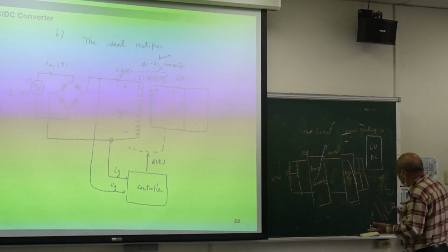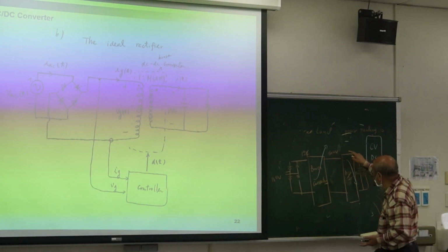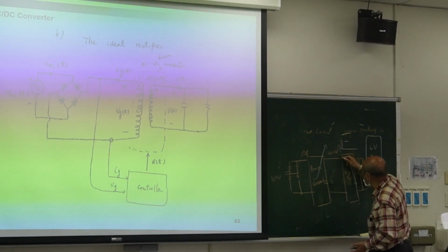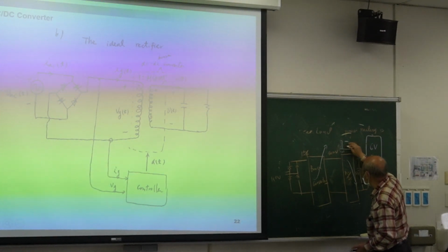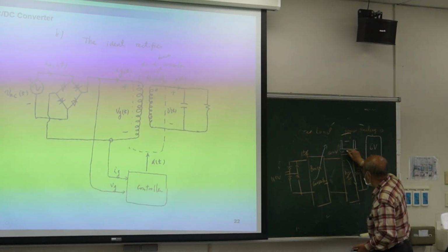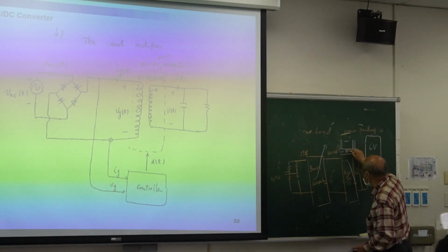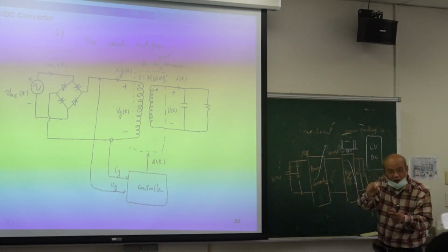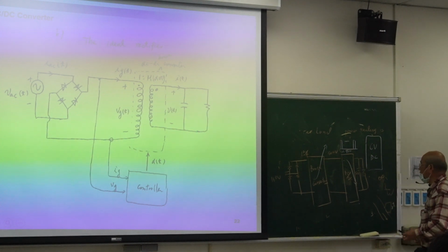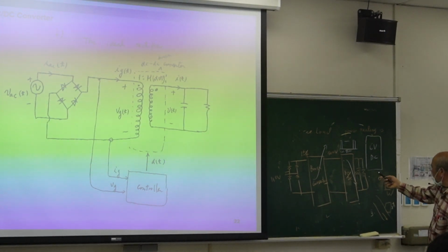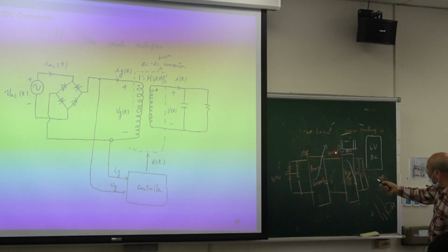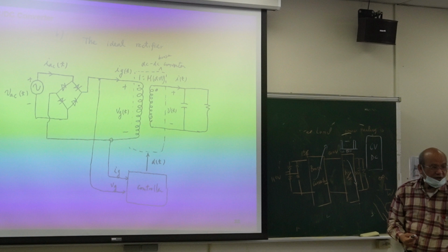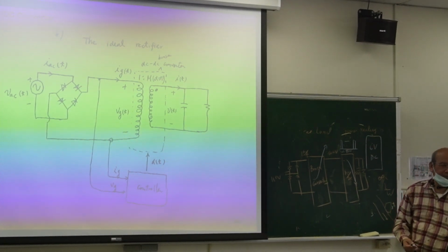And another problem is 400 volt to 5 volt. How can you control it? Maybe 1.5% turn on, then 98.5% turn off, right? So the duty is so small. Turn on duty is so small. Do you think this is easy to design for 400 volt become 5 volt? It is very challenging because duty is too short, right?